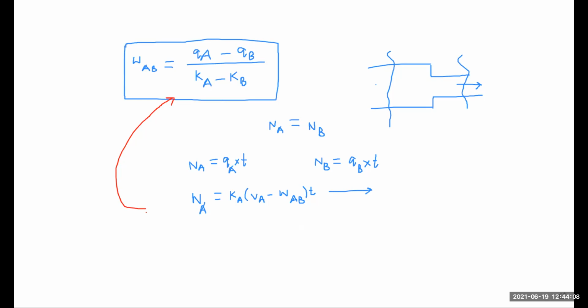Shockwave can move against the direction of traffic, as in the case considered previously. This type of shockwave is termed a backward moving wave. Shockwave can also be forward moving if it moves along with the traffic direction, for example when the width of the road increases suddenly or the traffic signal goes green from red. So basically, when the traffic signal goes from green to red, then we know more vehicles will be passing on our road.